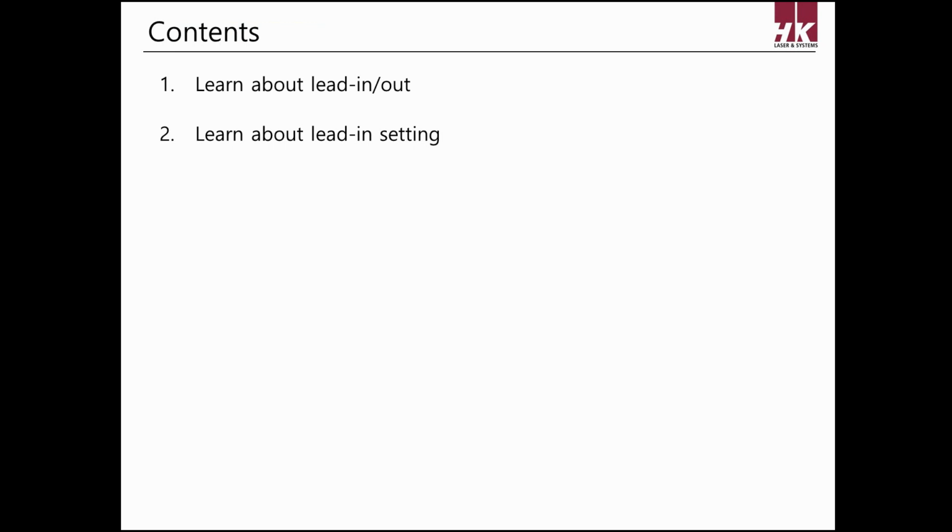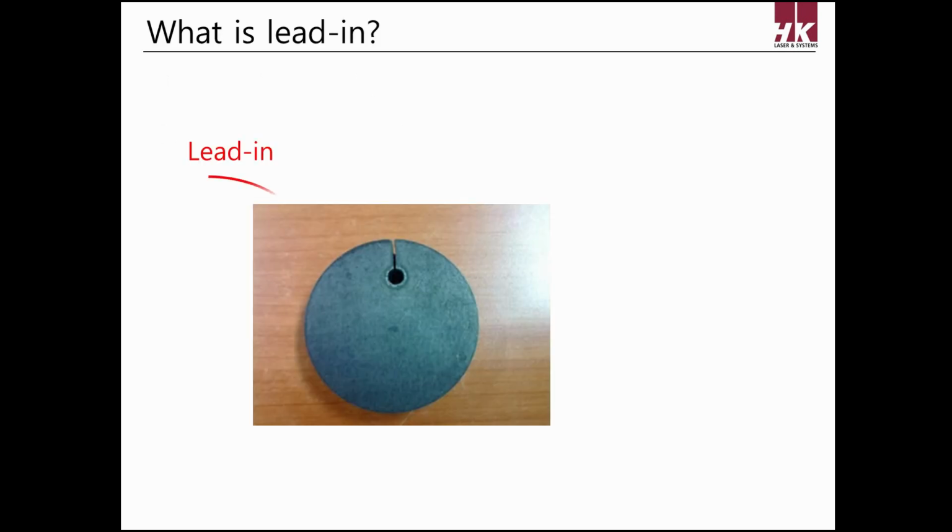This time, let's learn about lead in and lead out. Let's find out lead in and lead out that are mostly modified and applied by CAD/CAM workers and how to set them. In LANTEK, lead in is automatically generated after machining. Let's find out how to set lead in both automatic and manual, since it is applied automatically from material thickness dependent data.